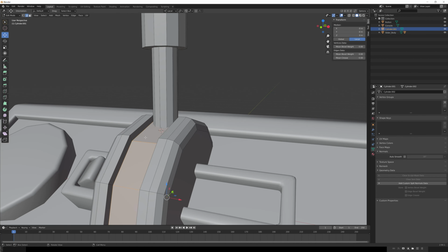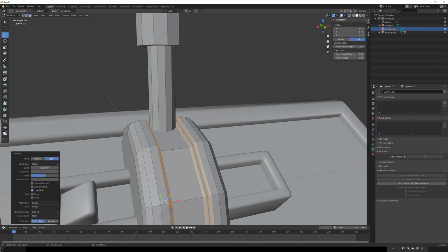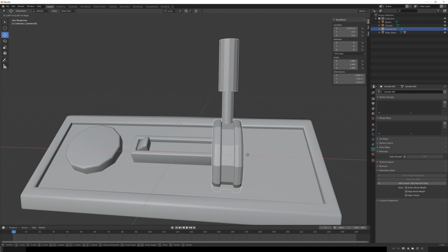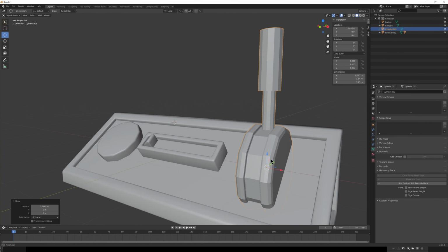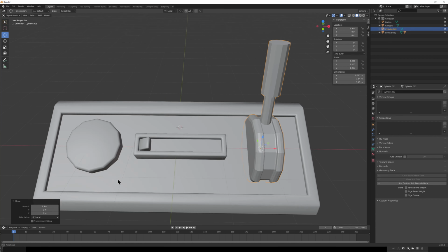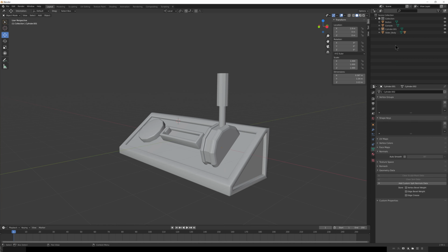And now, of course, we can arbitrarily add additional bevels or whatever you see fit to make this object look a little bit better. I'm going to go to Bevel and give it something like maybe that. There we are. And now we have our lever. So I'm just going to take my object and move it off to the side somewhere over here. We'll take a look, and I'm going to just move this to maybe 1.9. Now we've got our 3 different objects. We do need to do a little bit of cleanup really fast.